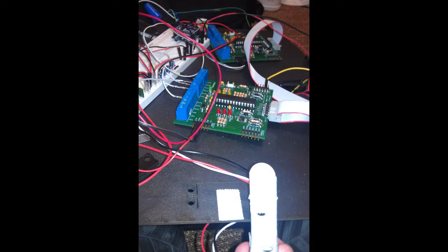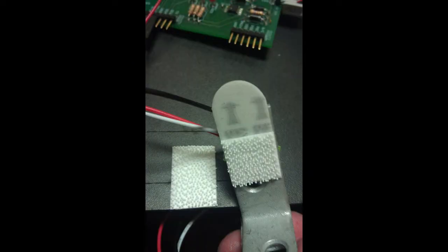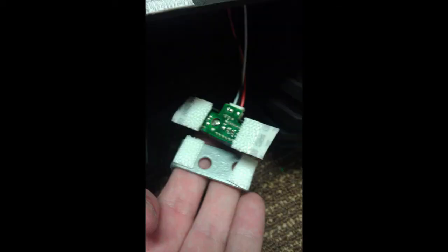For the safety of the sensors, we chose to use a two-part Velcro mounting system so that the bracket and sensor could detach from the rover and each other if a collision occurred. This is in contrast to a pretty common L-bracket approach where everything was screwed into the rover and sensors could break if a collision was forceful enough.